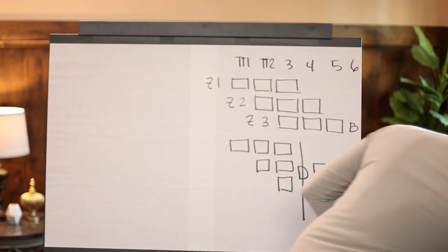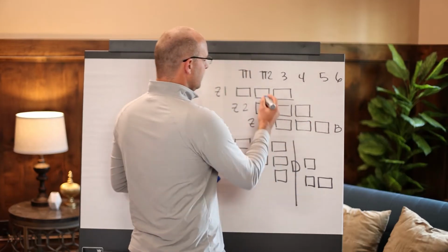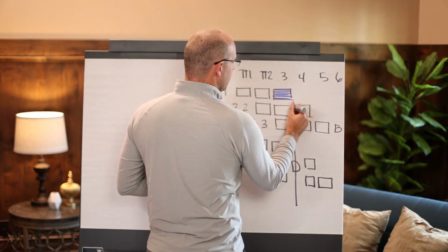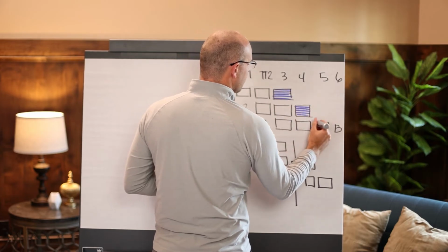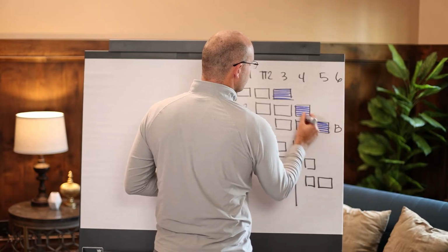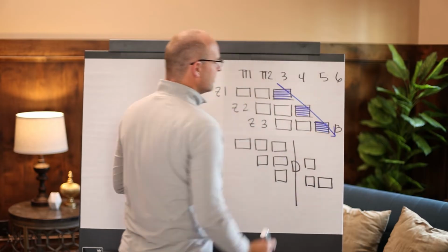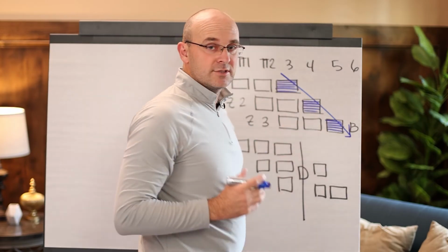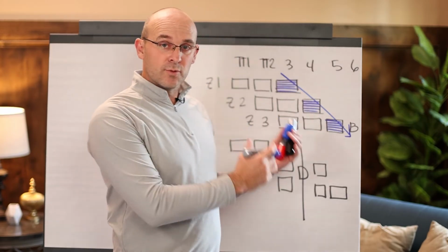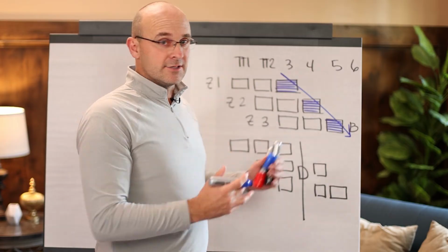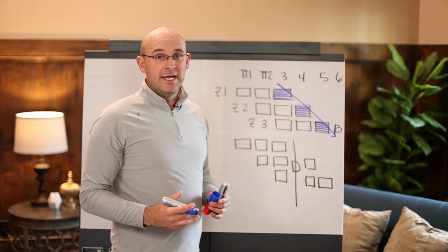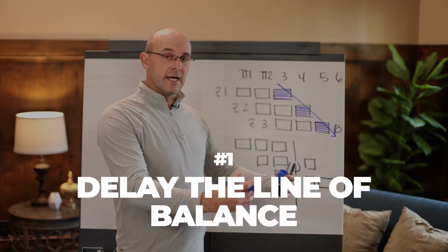So like we talked about last time, you will have a trade here that will cascade down to the right. And in this schedule, you have what's called trade flow. That means that that trade is flowing at a diagonal and it is moving from area to area in what's called one process flow, which is the real way we flow in construction. Now, the first consideration for a delay is to delay the line of balance.